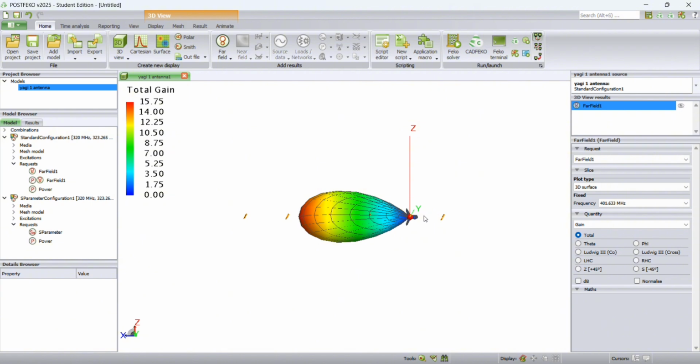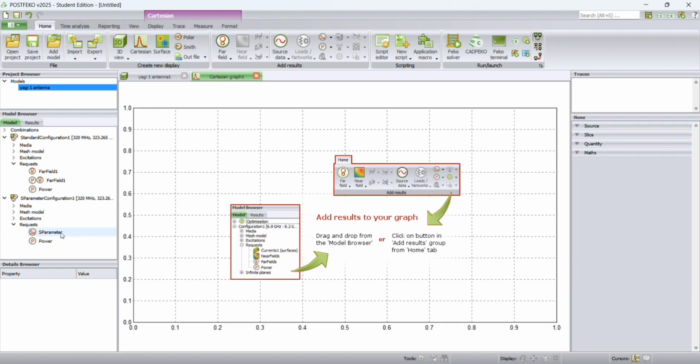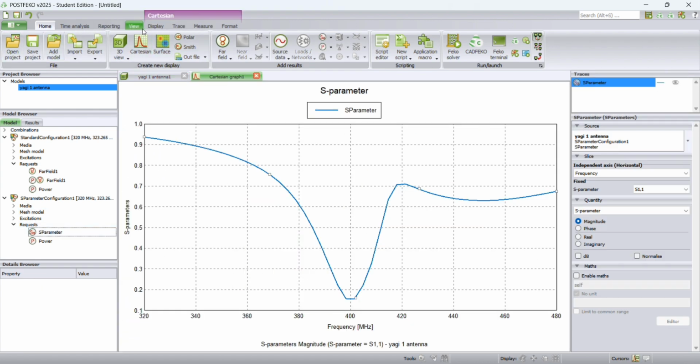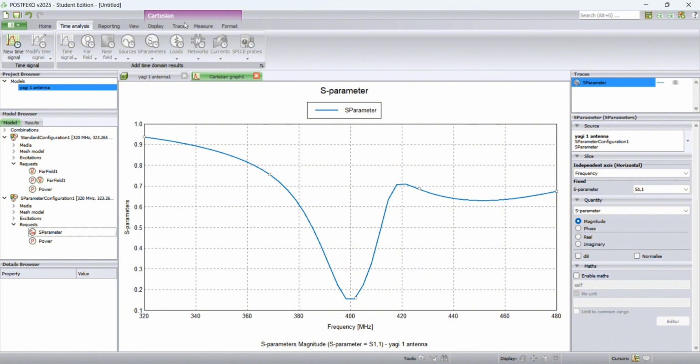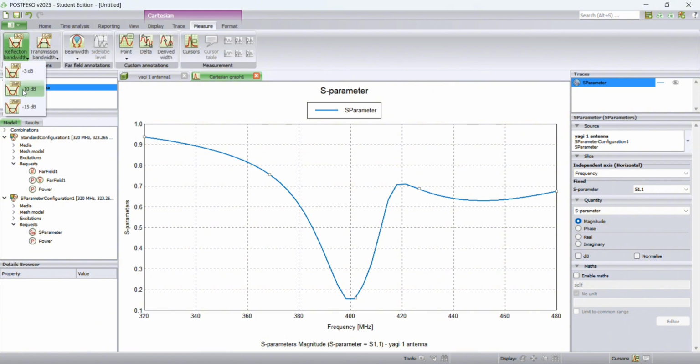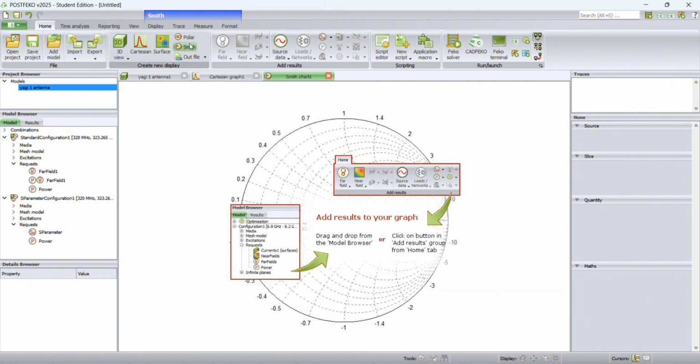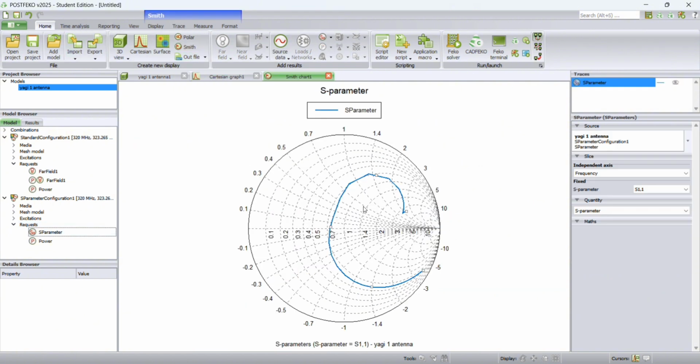After that we will give the Cartesian and give the S parameter configuration 1, and under it the request is there. The S parameter given means it will show the S parameter. We want to see the bandwidth, the reflection bandwidth. Give the reflection bandwidth.